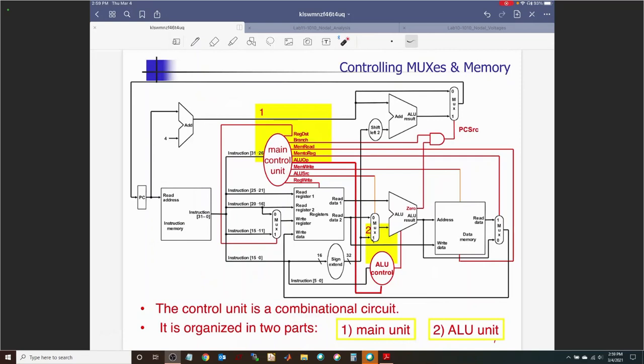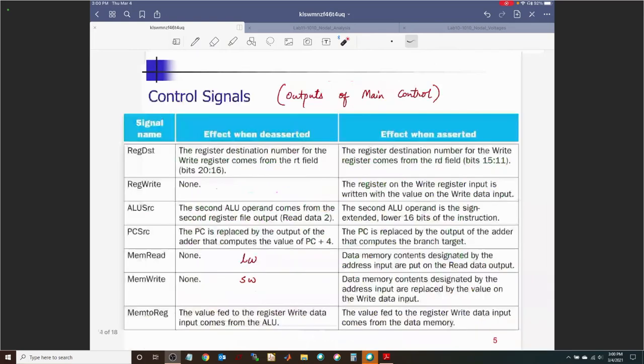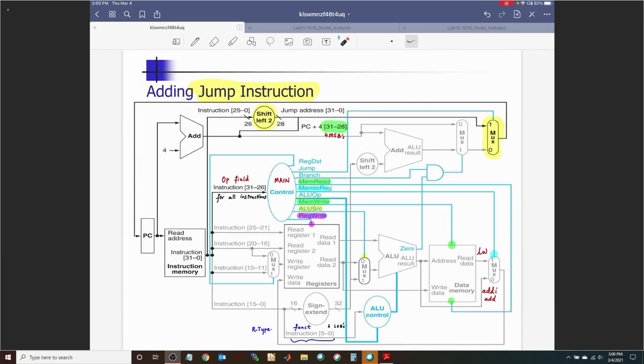Let's move on here. So before I go to the next slide, I just want to say, you see, the data path block diagrams can become a little bit too much information to look at in one slide. So what you will see is selectively some may not appear all the time. So for example, if you look at this, which particular instruction is missing from this block diagram? There's one instruction that we kind of added, a jump, right? Yeah, there's no jump because we are not taking the program counter +4 and we are not shifting it. Earlier we drew it up here, right? Remember that? We drew it up here, but we didn't include that later.